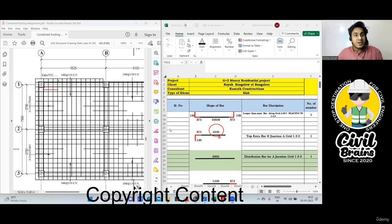Okay. Now I'll find the distribution length first. Whenever you put the distribution bar, your distribution bar will be from here to here. Only this much part for this slab. And then from here to here, this length I need to find. Since we took 1, 2 and 3 grids simultaneously, I'll calculate the length from here to here completely, and then from here to here completely. Then I'll deduct the middle of the beam, because in the middle part, your distribution steel won't come.